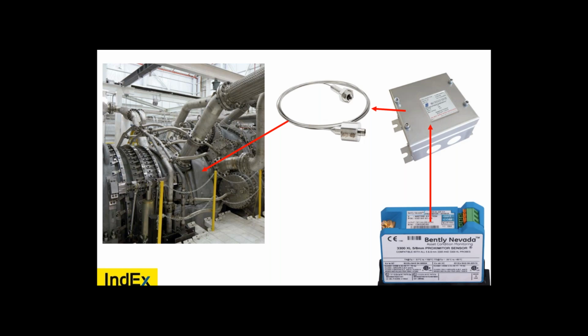IECEx is a voluntary system. So can an IECEx inspector, IECEx CoPC certified inspector, do ATEX inspections? Yes. It is much easier to go from a higher level of knowledge and understanding and higher quality management system to a lower level, such as Category 3, Zone 2 equipment being manufacturer self-certified, which is a lower form of certification.